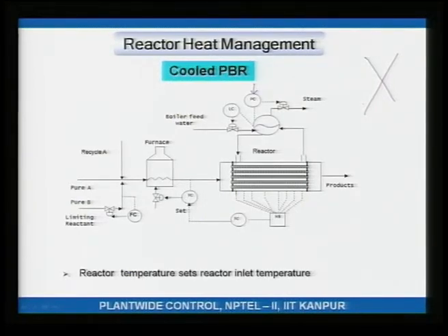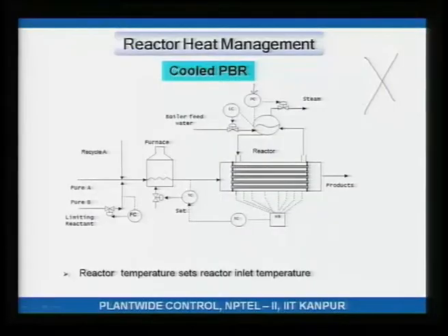You see, it is so much easier to make a fire than to douse a fire. And when I say a fire, fire may also be considered as a reaction. So, let us say there is a highly exothermic reaction. Because the reaction is exothermic enough, I am having this cooling circuit. If the reaction was not too exothermic, I would have just had an adiabatic packed bed reactor, right. So, there is sufficient exothermicity to justify this cooling circuit, that is why I have it. Now, since it is easier to light a fire than to douse a fire, what that means is, if the hotspot temperature is going up, let us say T hotspot is going up, that means fire is getting caught.